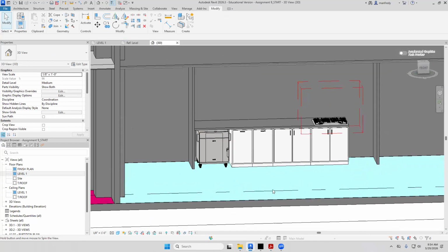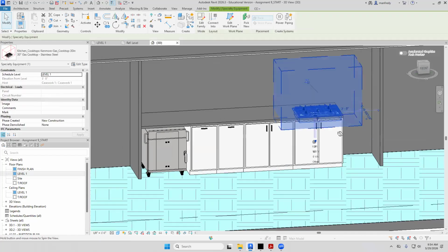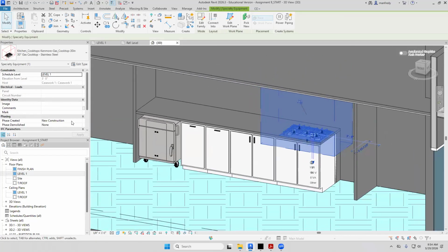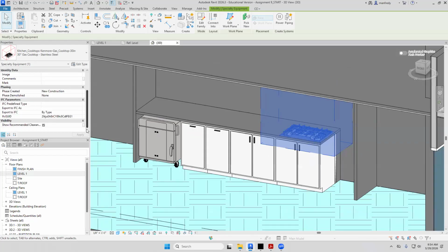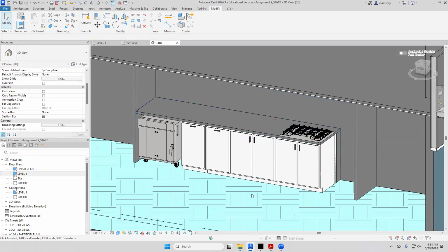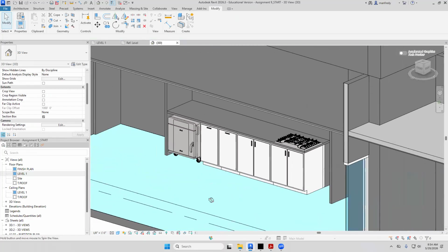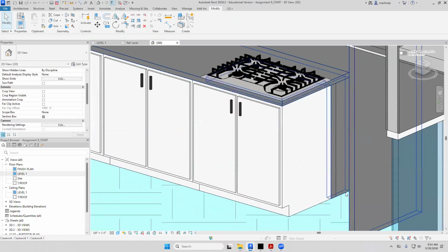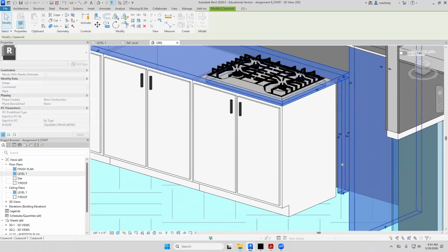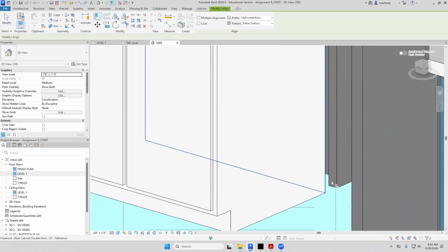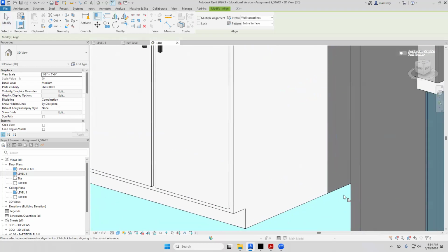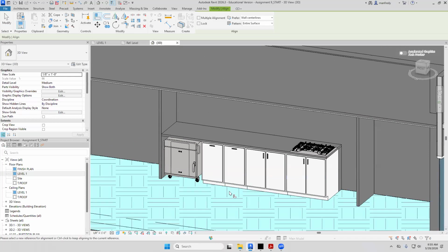This oven seems to have some more 3D lines here. You see this guy here? Again, I typically like these things to have a box that hides their visibility. Here, see show recommended clearance? Checkbox. Luckily, I can click on that box and turn it off. If they don't, I would erase it because I don't want to see it. Every family is different; whoever makes them makes their own decisions. Looks like this is too big. I went a little too far here, so I'm going to pull this back and line it up to the back of this. So there you have it.